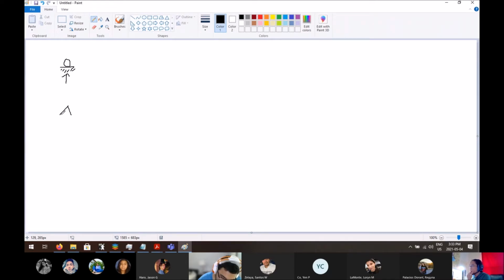You have a pin. There are two reactions, in the y and the x. And then you have fixed points. They have a reaction in the x, in the y, and a moment reaction. We'll get to moment in a bit, because that is very important.